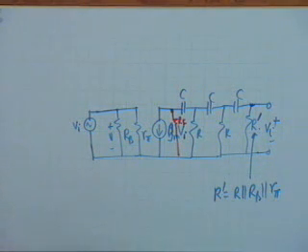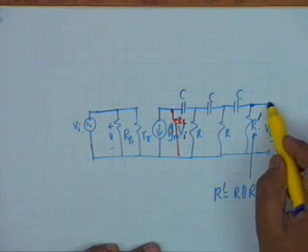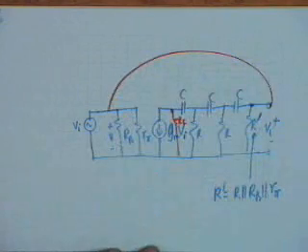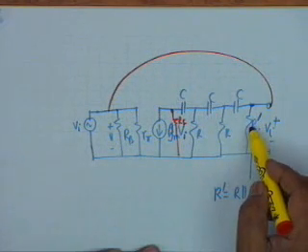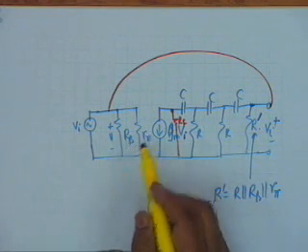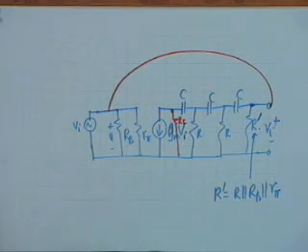Is the point clear? No? After all, in an oscillator, you are going to connect this point to this point, and therefore this last resistance R shall be in parallel with RB and R pi, and you have to analyze under that condition.